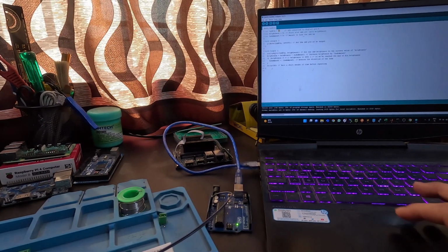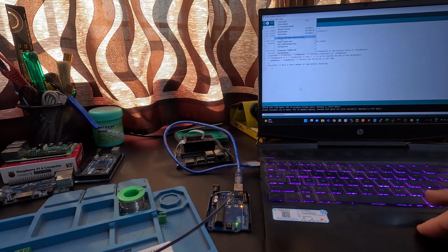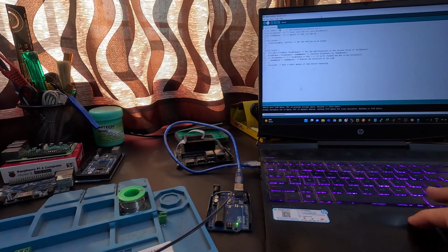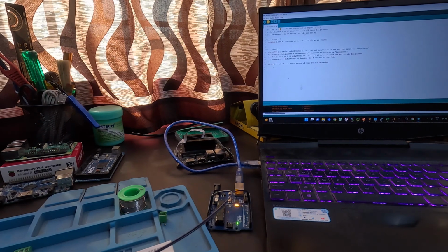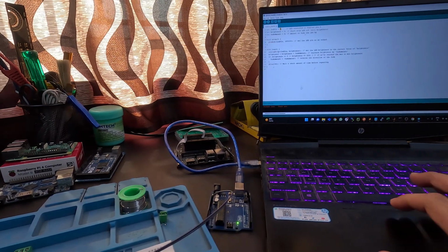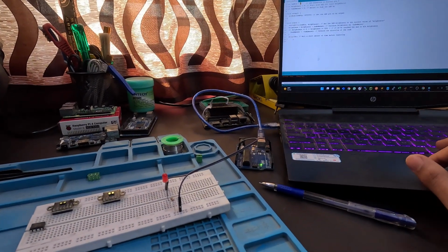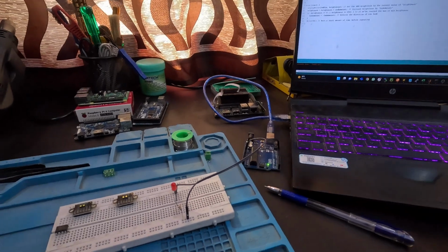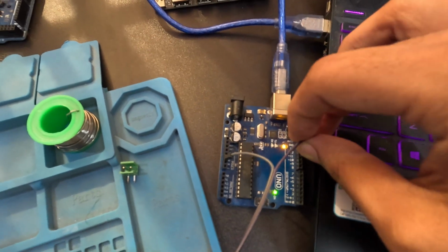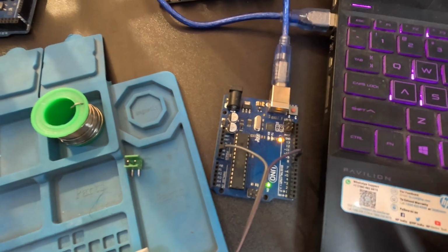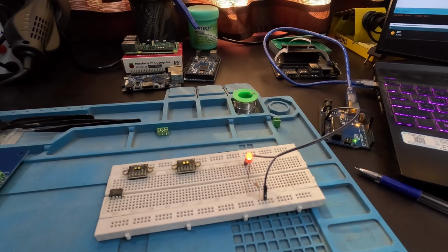Now we are uploading our code by clicking the upload button. Before that we will check our tools and the ports. Then we click on the upload button, and it starts uploading. Uploading is done. As you can see, the LED has stopped blinking now because it is connected to pin 13. Now we will connect from pin 13 to pin 9. I have moved the connection from 13 to 9. Now you can see the LED is fading,